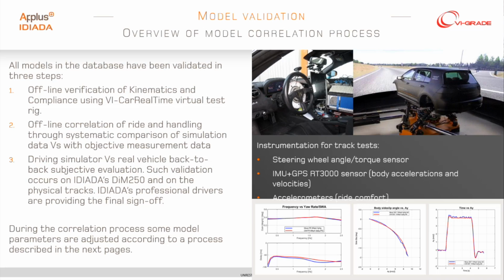And once we complete this phase, then we are ready to move to the driving simulator and perform the last step of the validation, which is with the help of a tuning engineer, a subjective driver professional. We get his feedback, her feedback, and we finalize the tuning of the model so that we can make sure that everything has been extensively checked, and we go back to the offline and the KNC correlation to make sure that everything is aligned. And by that time, after those 3 steps, we are able to sign off the model and say that, yeah, this is a really good model.